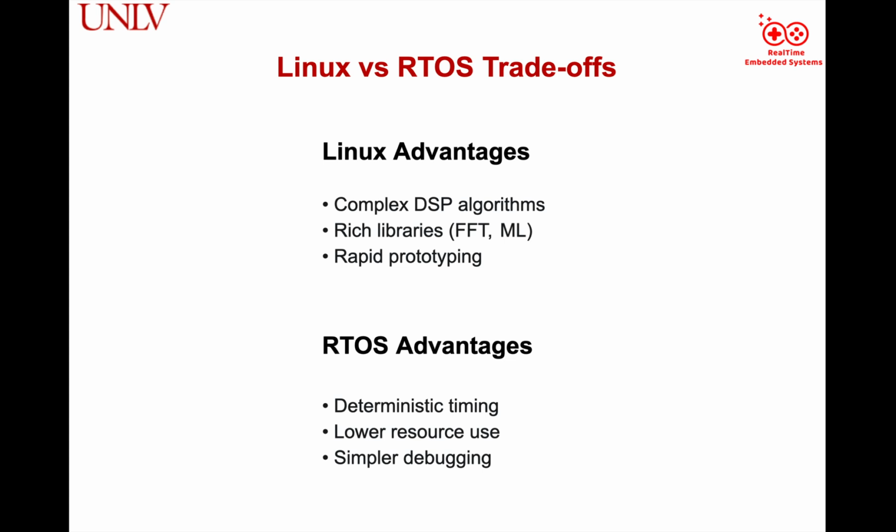So let's talk about the Linux versus RTOS trade-off. Linux is ideal for complex DSP algorithms, library access, and rapid prototyping. RTOS, however, provides deterministic timing, lower resource use, and simpler debugging, making it suitable for different applications.